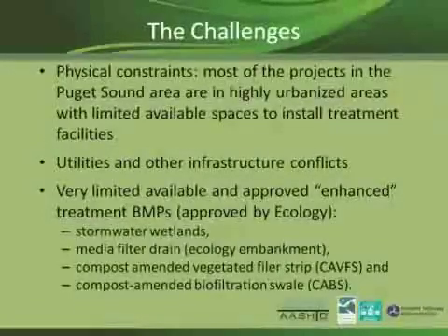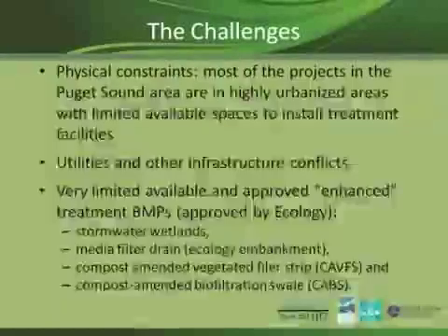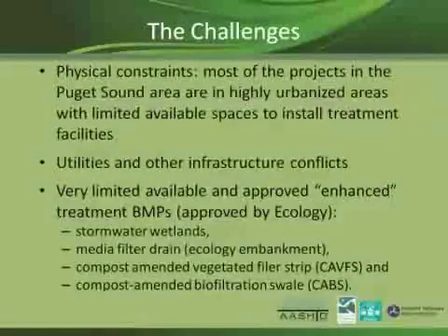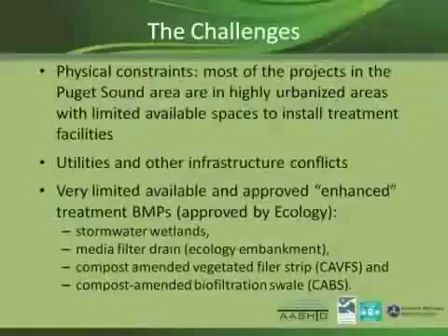This one is just a regular typical biofiltration swale, but we put compost amended soil on top of the existing soil, and we till it in with the existing soil. By doing that, I think it can remove dissolved metals better than a regular biofiltration swale. Next slide.